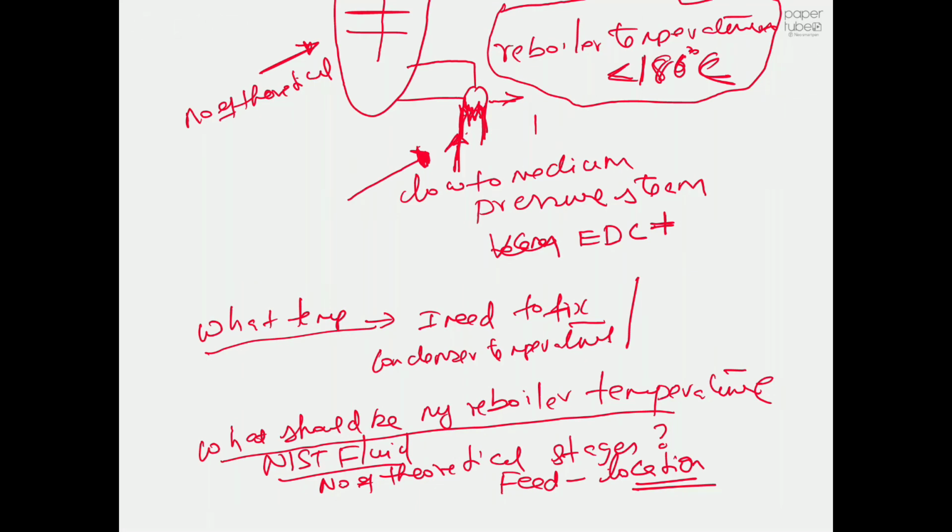And obviously you should know how to design the distillation column. For that we will rely on Aspen HYSYS. I will make a separate video just on the distillation column, because it will go for roughly 30 minutes. You will learn how to use the shortcut distillation method to get some parameters, and based on those parameters, we will build a rigorous distillation column. So these are the information that you need.